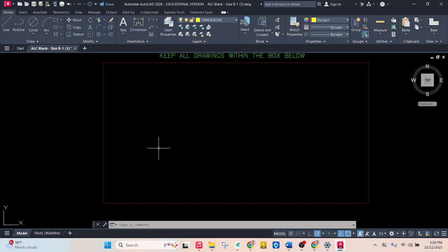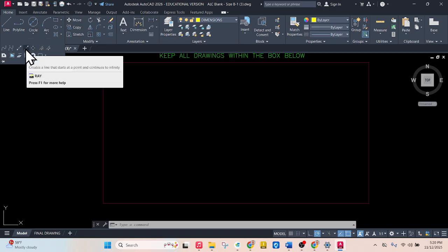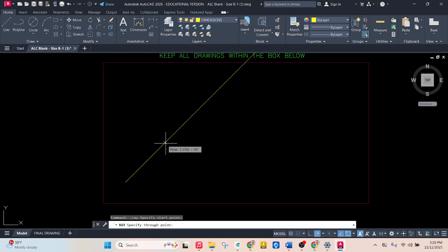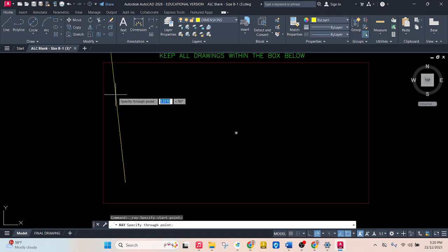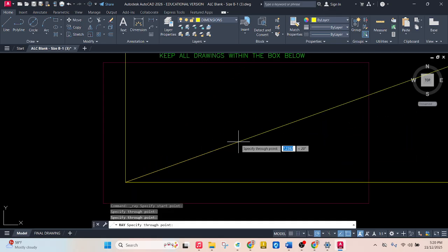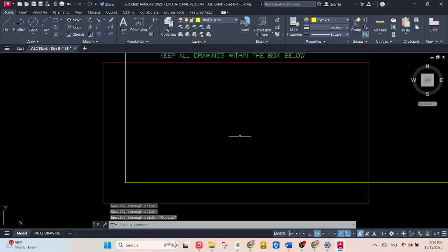Good. So first thing I'm going to do is draw some lines, and I'm going to use a new tool we haven't really used before called Ray. And Ray is awesome, because it will draw a ray. It has a starting point, and it just shoots off into space like that. I want this to go straight up like that, and the other one goes straight over like this. And I can escape. That is my plot that I'm going to be using.